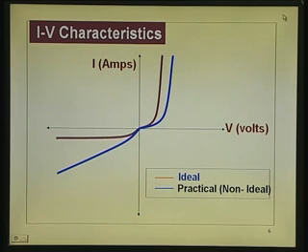The actual thing that happens is, the device characteristics, this curve is ideal. I naught is saturating, and in the non-ideal case it does not saturate, it keeps on increasing. So, we will see what are the causes of that. In the forward case, we just now saw the current increases less steeply compared to the ideal case, so it is slightly shifted to the right, as I put. Actually, it will still be exponential, but less steep. Instead of e to the power of V by V t, it is e to the power of V by n V t. So, that is the practical situation, this is ideal.